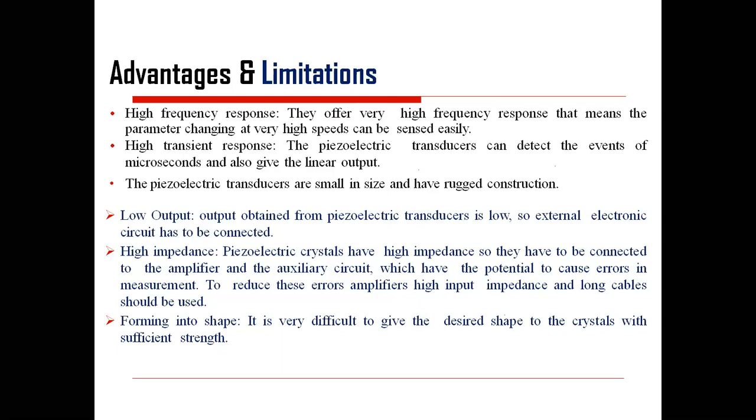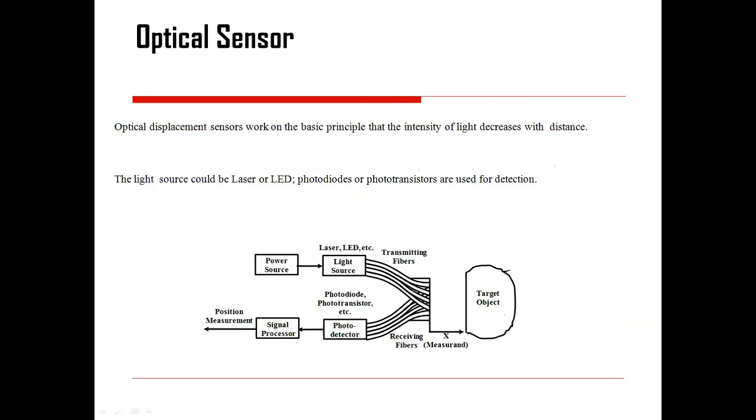Then the second limitation is high impedance. Your piezoelectric crystal has a high impedance, so it has to be connected to an amplifier and auxiliary circuit, which have the potential to cause error in measurement. So to reduce this error, an amplifier with high input impedance and long cables should be used. So remedies are also provided for this aspect. And one more, which we discussed in the properties: it is very difficult to give the desired shape to the crystal. Okay. Now another